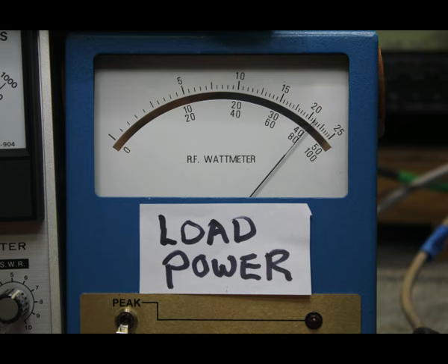We can if we use a VNA at the starting end because of how the source behaves in the VNA. But this is mostly a source problem. It's not a loss problem in the cable. It's not reflected power bouncing back and burning things up and doing this and that. It's changing the impedance in the cable, and it barely changed the loss in the cable, going from a 1-to-1 standing wave ratio to a 10-to-1 standing wave ratio.